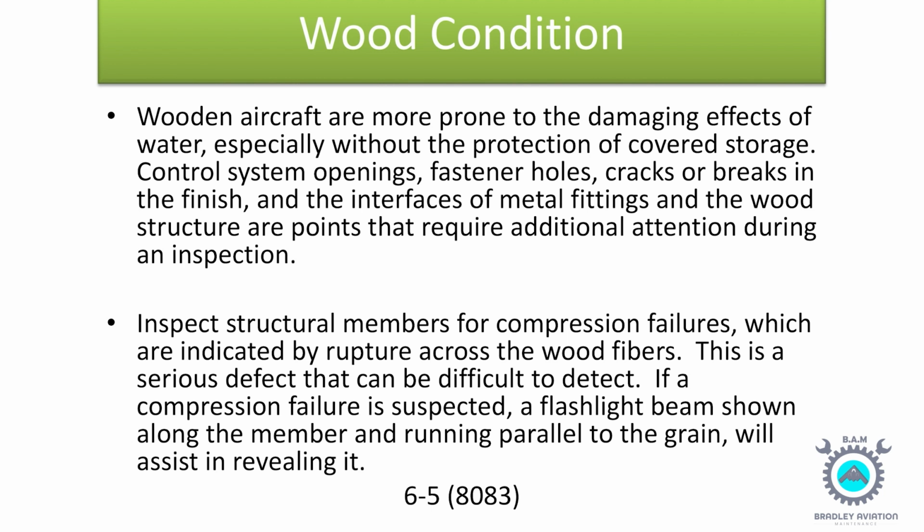Inspect structural members for compression failures, which are indicated by rupture across the wood fibers. This is a serious defect that can be difficult to detect. If a compression failure is suspected, a flashlight beam shone along the member and running parallel to the grain will assist in revealing it.